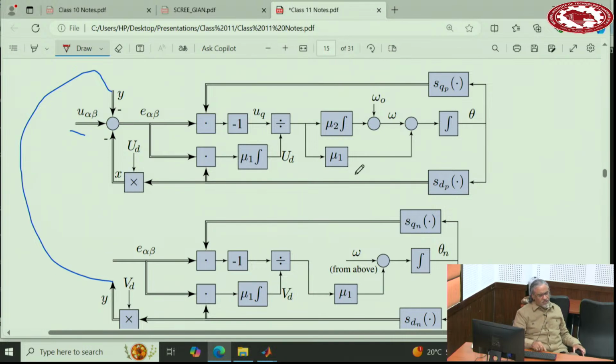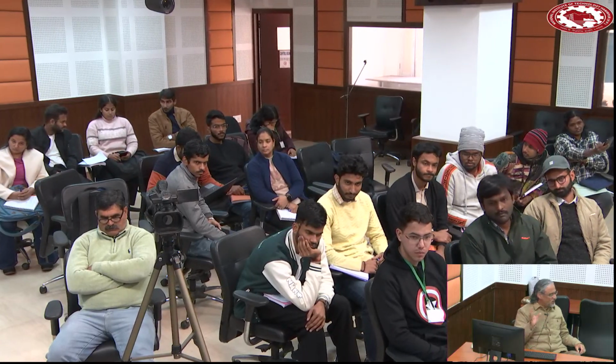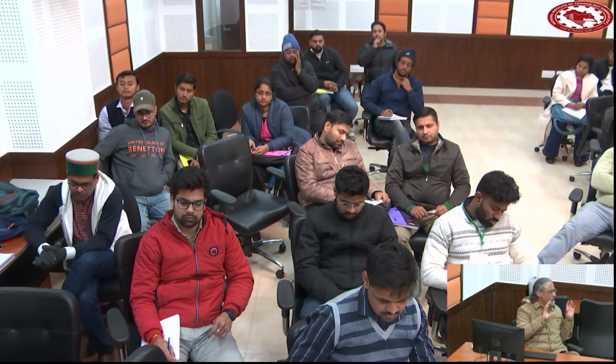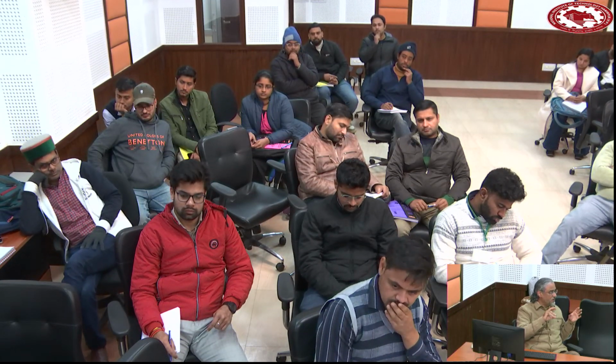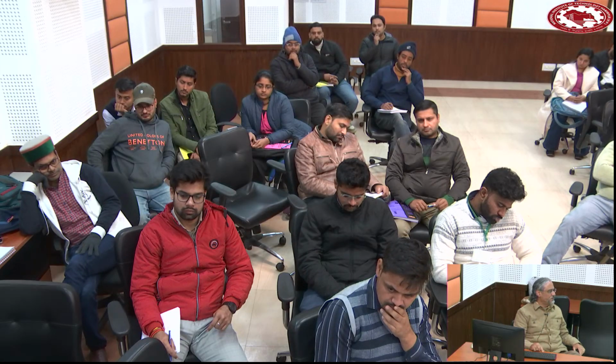But my experience, I'm going to tell you, if you do a good, correct simulation in continuous time, compared to digital time, the only thing that you are missing is that one sample delay. And then you can always go back to your simulation, and after your continuous time controller, put one sample transport delay. So this is, I would say, chiefly equivalent to a digital control. If your simulation runs with one sample delay, 1.5 sample delay, in continuous time with no problem, it will run in digital without problem.